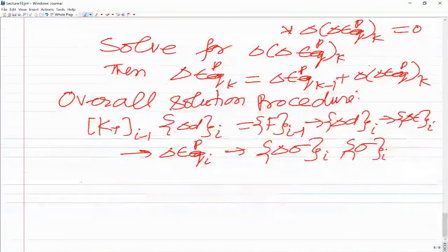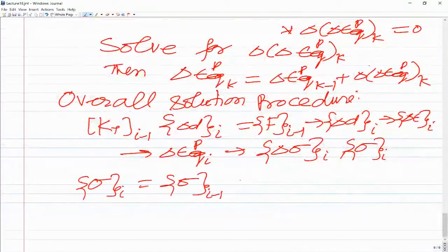and then you go for the next iteration till the solution converges. Of course, for the total stress, at each Gauss point you will write sigma_i is equal to sigma from the previous iteration plus delta sigma_i calculated over here.